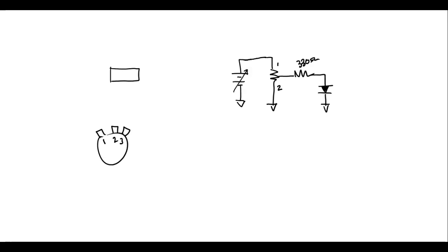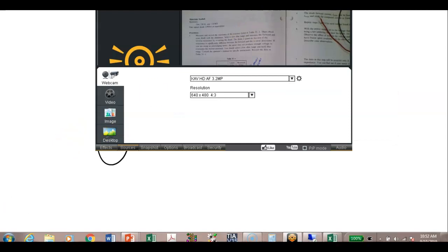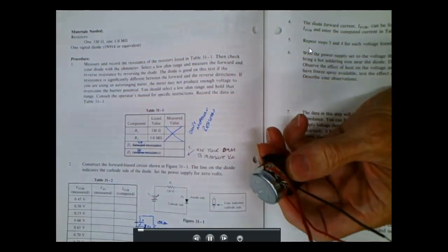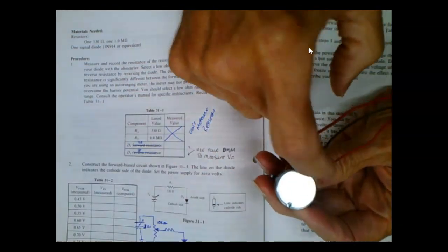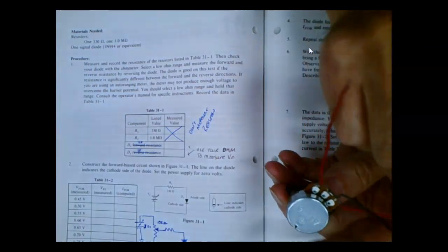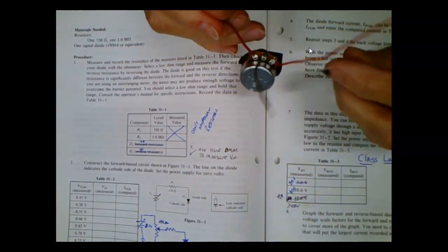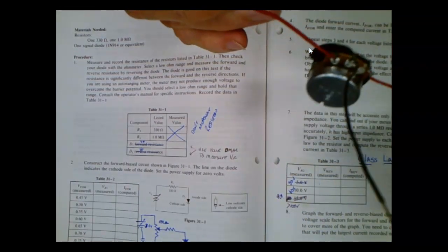Now what you got is this is where we got right here. We got 3 wires coming up because we got to put this into the breadboard, right? So this is the pot, right? 1, 2, 3. This is the wiper. So this is going to go to the 330 ohm resistor. This right here is going to go across your power, the power supply on the train. So both of them are going to go to the power supply. No, you got 2 going to the power supply.